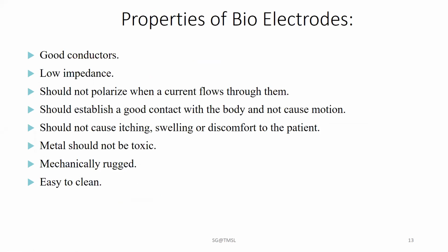So the first property is that they should be conductors, with low impedance, and they should not polarize when a current flows through them. And there must be good contact with the body, and it should not cause any motion artifacts. It should not cause itching or swelling or discomfort to the patient. It must not create any irritation to the patient.